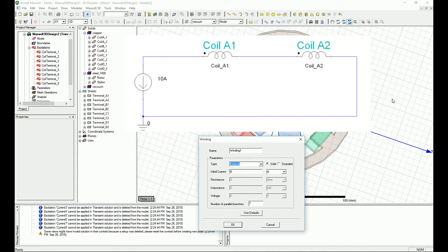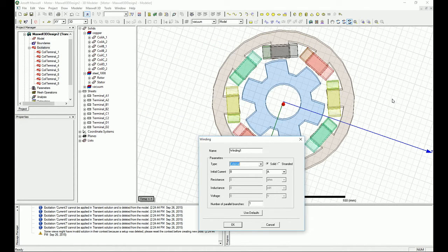gate, and then you know, the PWM, whatever you want to put there. And then what you do is you just drop a winding there with the same name, or you can actually do a trick where you open up the circuit editor from this winding, and you basically have the windings that are associated with this coil or this Maxwell file right in the circuit editor, and you can put whatever you want to do, and you are no longer constrained to this series or current or voltage type of excitations. You can have whatever you want to do, and that would be the external type. And as you can see in the external type, the only thing you can talk about is the initial current that is in your coil. That's it, nothing else. And everything else is done outside, and you can do it totally customized. I will give you a tutorial on that as well. But let's go with the voltage type and basically start our simulations right there.